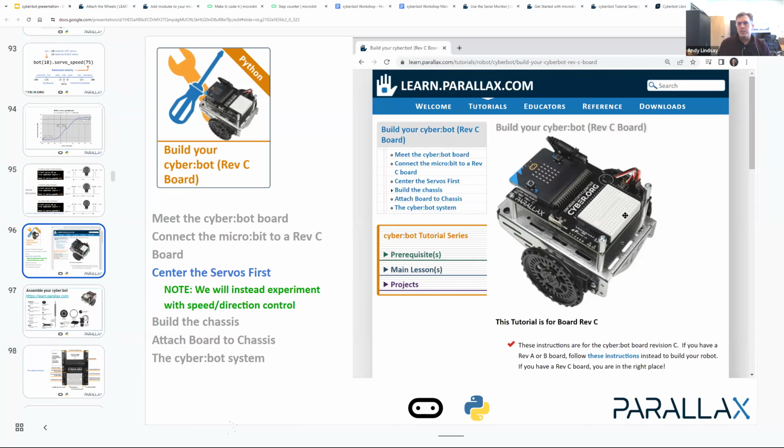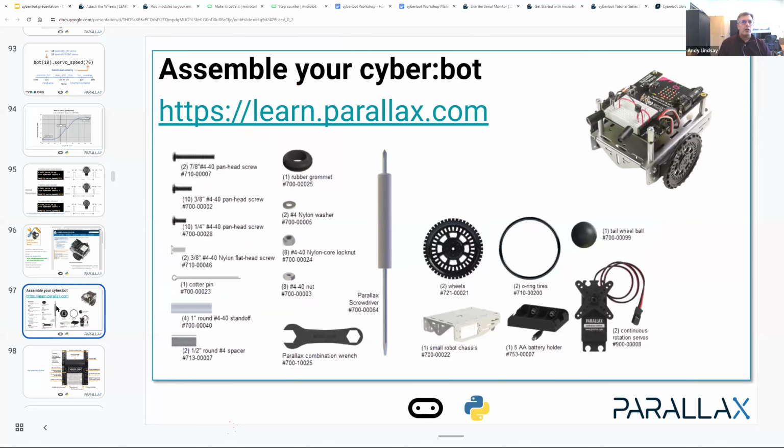So position 1 is nice for loading the script, and if you have some sensor circuits, you can actually test the sensor circuits without the servos trying to blast off and jump off the table on you. Then once you're happy that the sensors are working, you can set the power switch in position 2, and then it'll start moving because position 2 also includes the servos. It gives power to the servos as well as the circuits. Yeah, I agree. It's a nice feature.